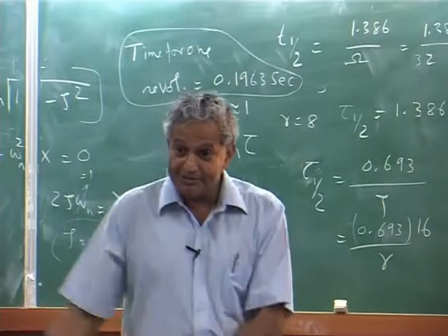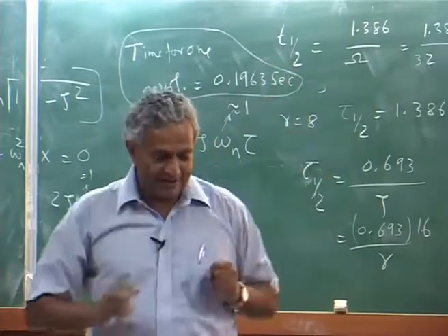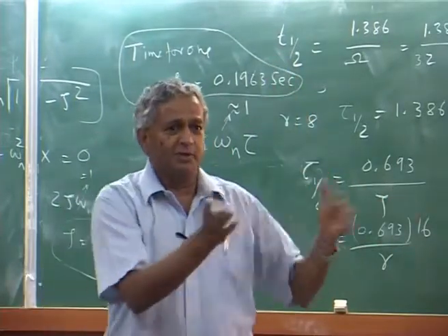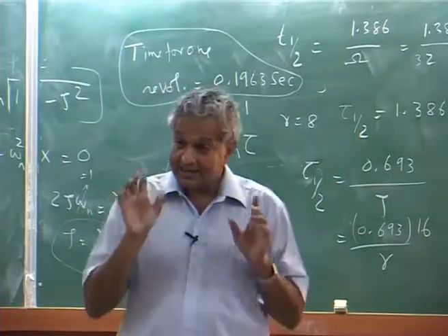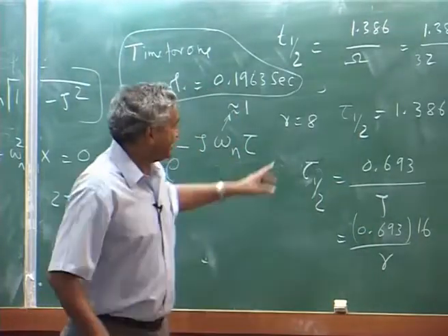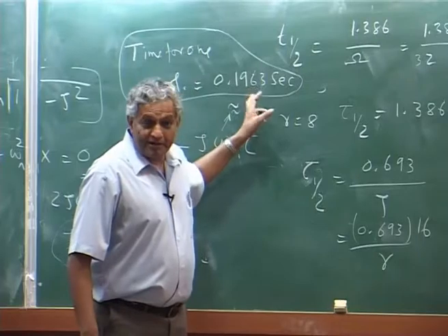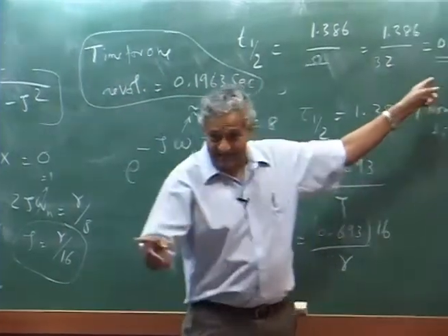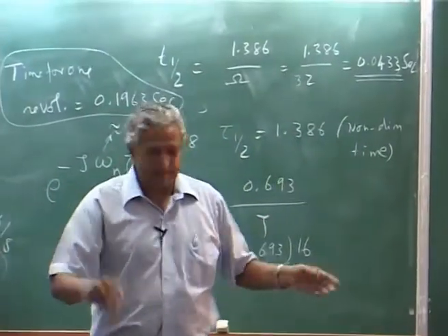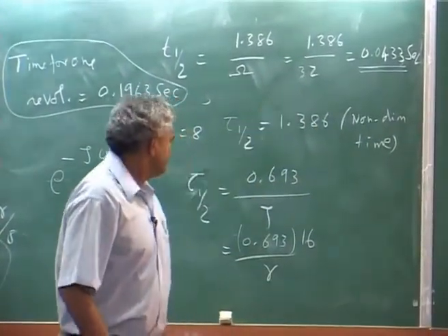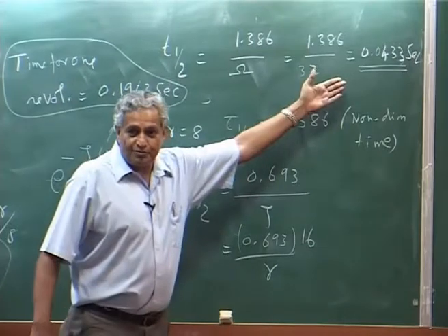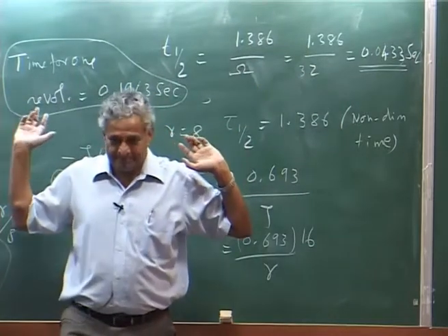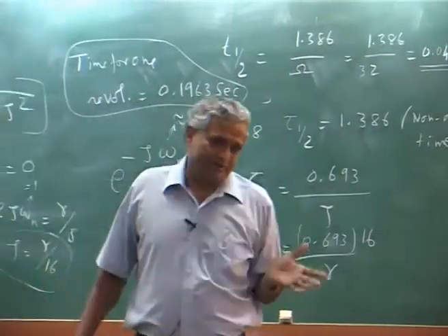Not that the flap dynamic equation is thrown off, but I say I give an input and instantaneously change my loads. That is because of this. In one revolution it takes about 0.2 seconds, whereas the flap decay, the response time constant, is that small value 0.04, which is about 20% of this. It means it responds very quickly.